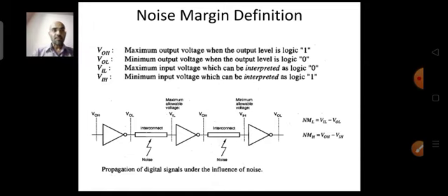In an analog circuit, if we change the input voltage by a small value, then the same change is reflected on the output side. But we go for digital circuits basically for this reason only, because digital circuits provide better, or higher, noise margin compared to analog circuits. Because of that, if there are any small variations on the input side, the output doesn't change and remains the same as desired. That is a very important thing.